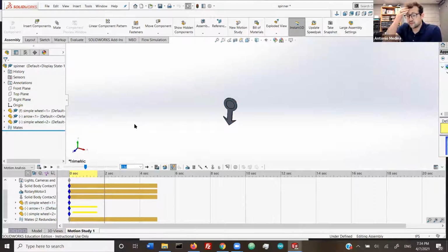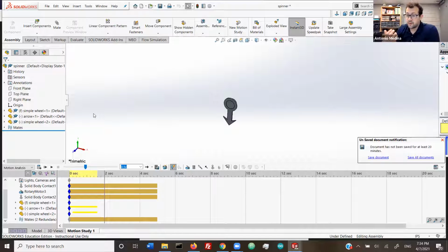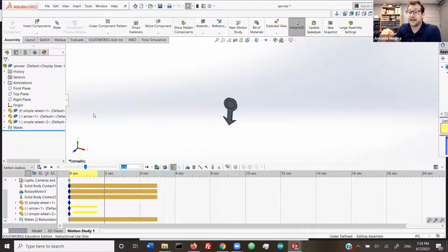So with stress and strength simulation, you can add a very specific material, you can say 6061 aluminum T3, whatever, right? But in motion analysis, it's really lacking there. It's much more for generalizations than specifications. I do know that SolidWorks has an additional package, like SolidWorks Pro, and then you can add any material set properties to motion analyses. But at that point, you're working with a large scale engineering firm where that's your job, and you're getting paid to do motion analysis on this sort of stuff, which is cool. But I'm not good enough to do that.